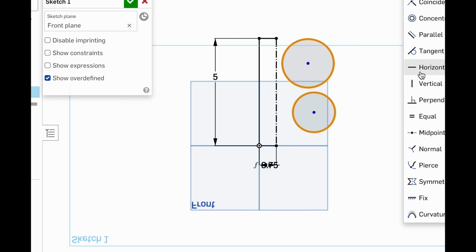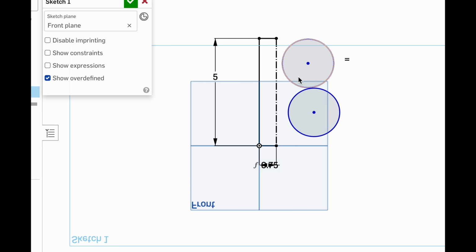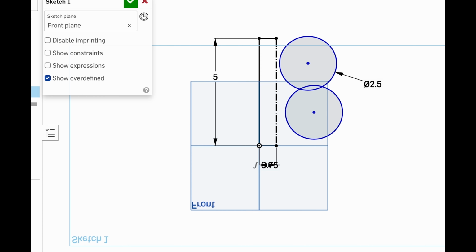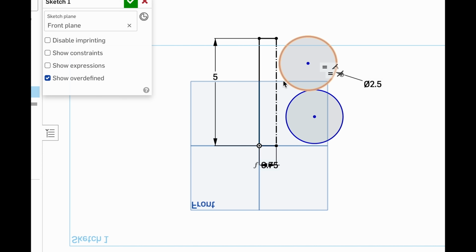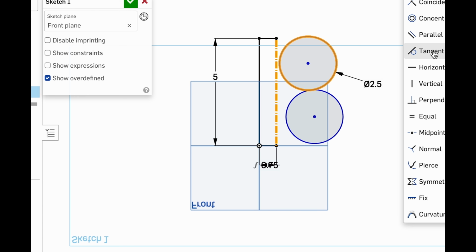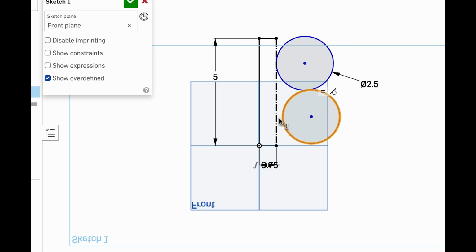And remember that the bumpers are backed by a 3/4 inch piece of plywood, so the box rectangle that you see in the back right now, that's gonna be our plywood. And next, we have the pool noodles, which are 2.5 inches in diameter. Right now, I'm just setting them equal to each other, so I only have to dimension one of them.